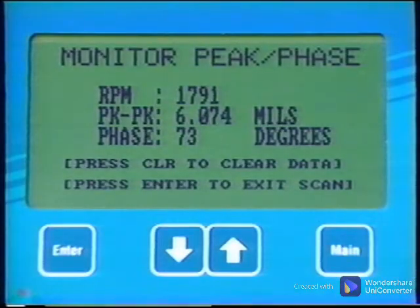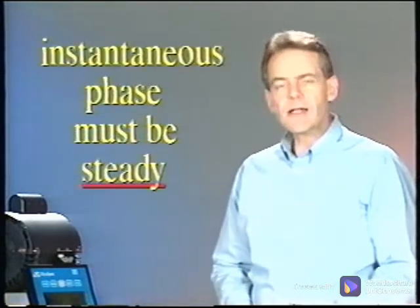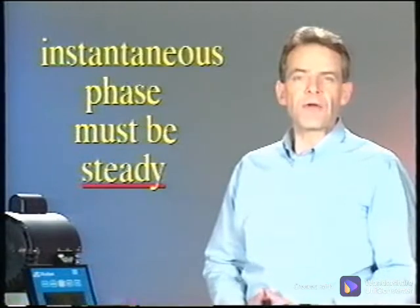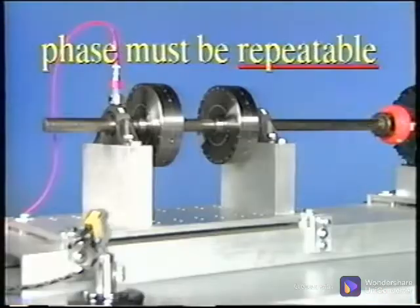When making the phase measurements, monitor each point long enough to ensure the readings are steady. If there is mechanical looseness, the readings may bounce all over. If there are other frequencies spaced closely to the turning speed peak, the phase may slowly rotate the full 360 degrees. The instantaneous phase readings must be steady within a 30-degree range before a successful balance job can be performed. The phase must also be repeatable from startup to startup.